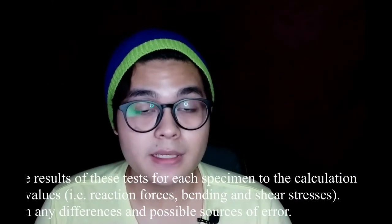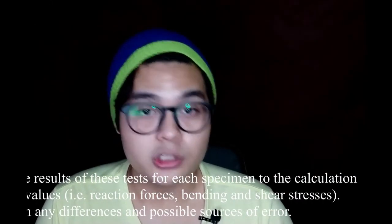Steel and brass have identical data, which is shearing force, bending moments, Vmax, Mmax for 450 mm. This is because of the same reaction force that they both have. Besides 450 mm, there is a lot of difference, even though the calculated reaction forces are the same due to the same load used.